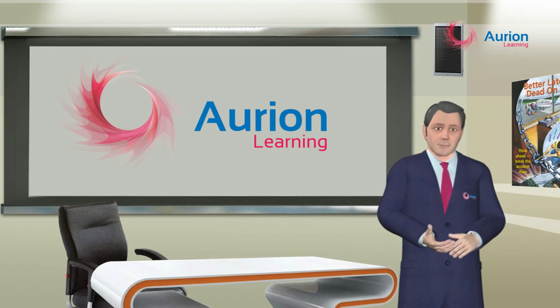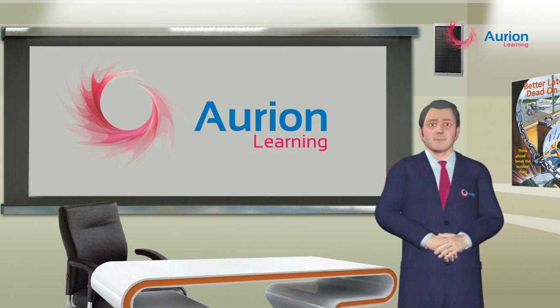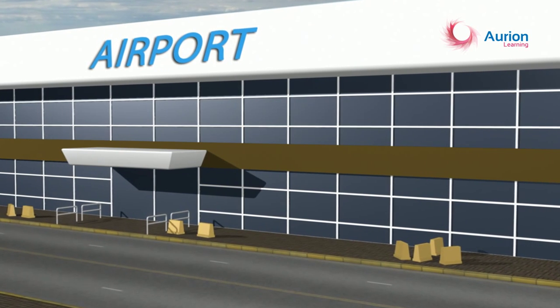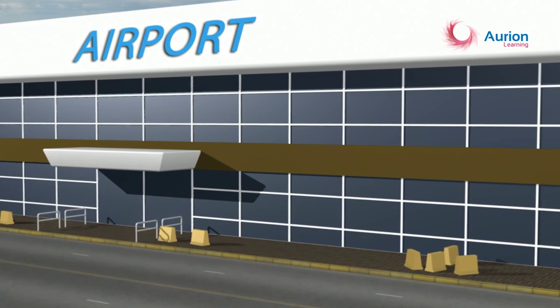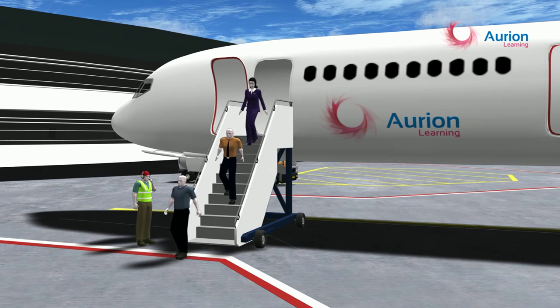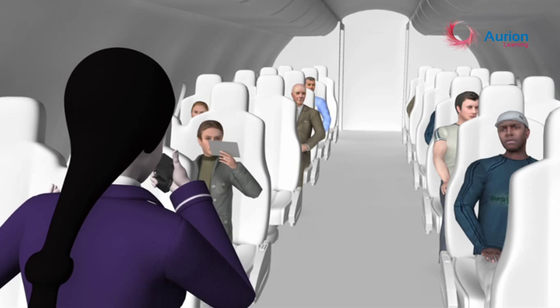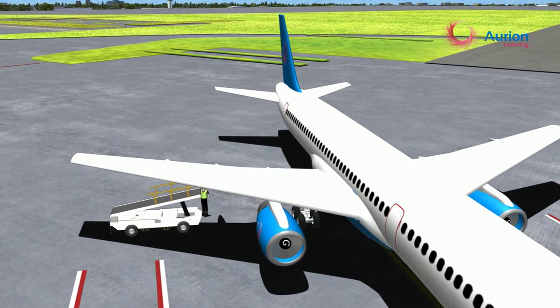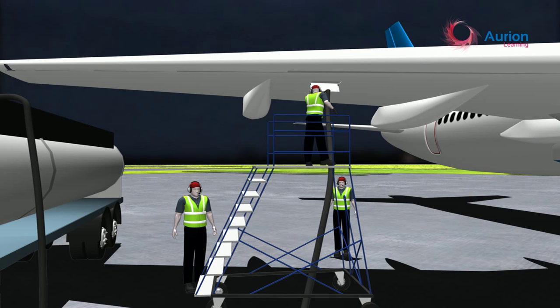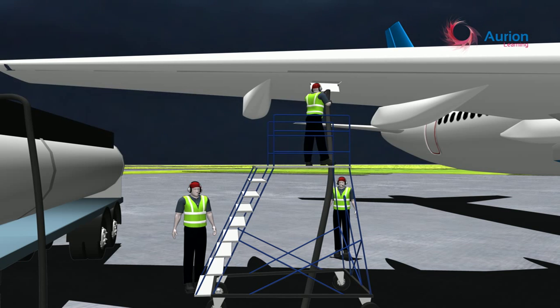To avoid any such accidents, certain precautions must be taken while fueling and defueling. Based on the local requirements, the airport should give clear guidance on its policy regarding the fueling of aircraft with passengers during disembarking, embarking, and transit. Ground support equipment must not be parked under the aircraft wingtip fuel vents. It is prohibited to fuel an aircraft when there is a thunderstorm in the airport vicinity.